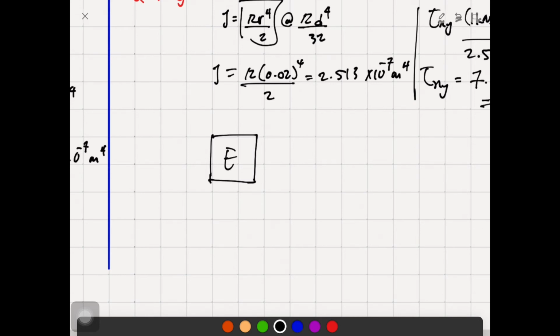We're going to list down all the stresses, put them there, with x and y as the axes. Here we have a positive shear stress, and the magnitude is put in here. This is tau xy, exactly what we have just calculated, 7.96 megapascal.